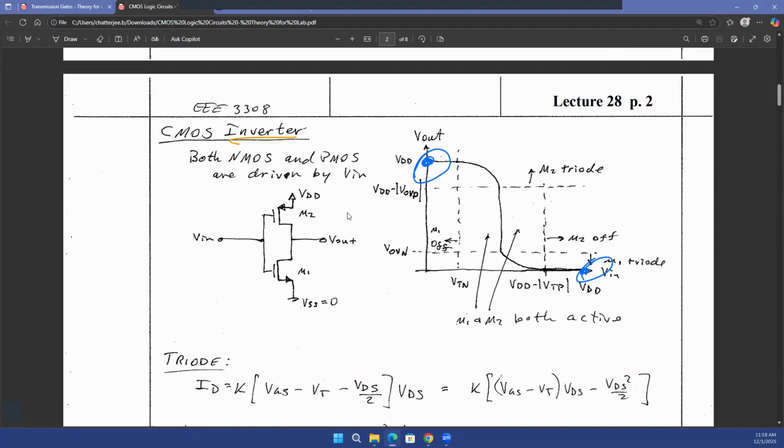This is different from analog circuits. Remember that in analog circuits, for example, let's say you had this common source amplifier. So let's say I have a current source on top, and then I applied an input at the gate, and then I have my source connected to ground. In a common source amplifier, you're always drawing this current. You're continuously drawing this current.